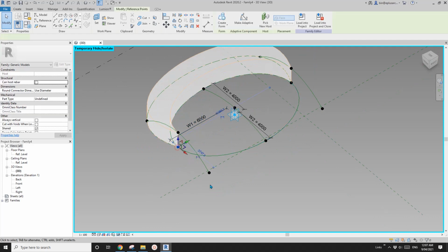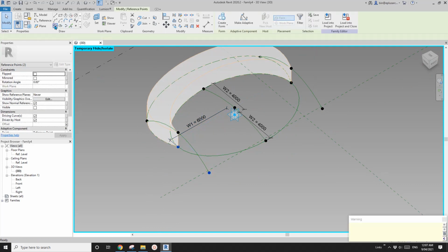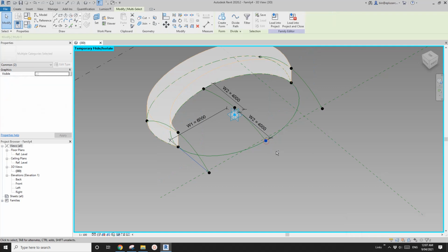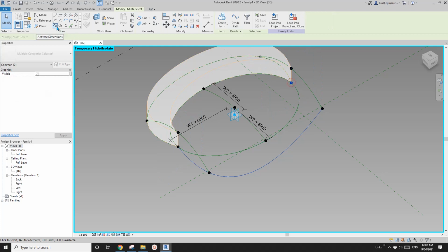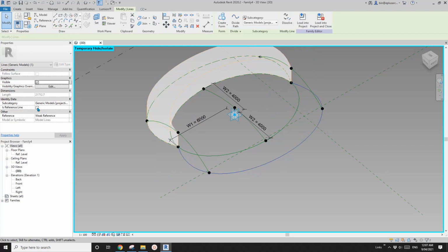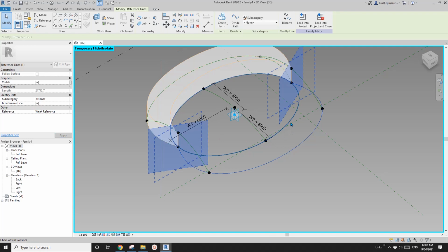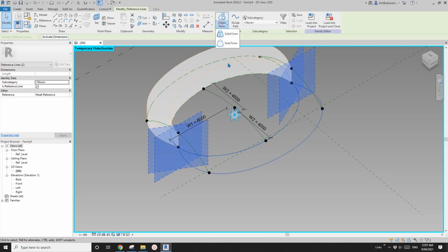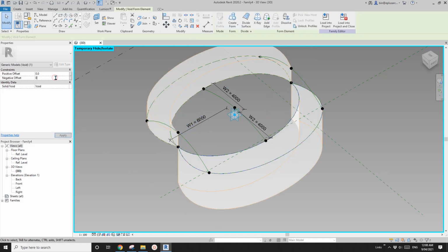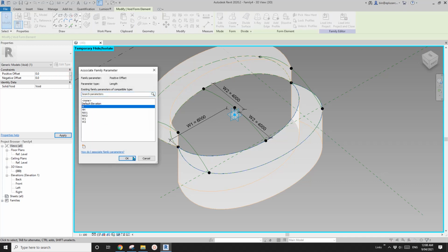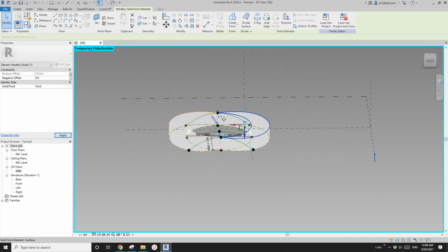So select this point together with this point, spline together with this. Oh no, sorry, not this one. Shift deselect and Control select this one, spline, and Control select this one, spline, and change it to reference line, and tab, Control select, and create a void on the left, change it to 0, link to H. So now we have two voids.